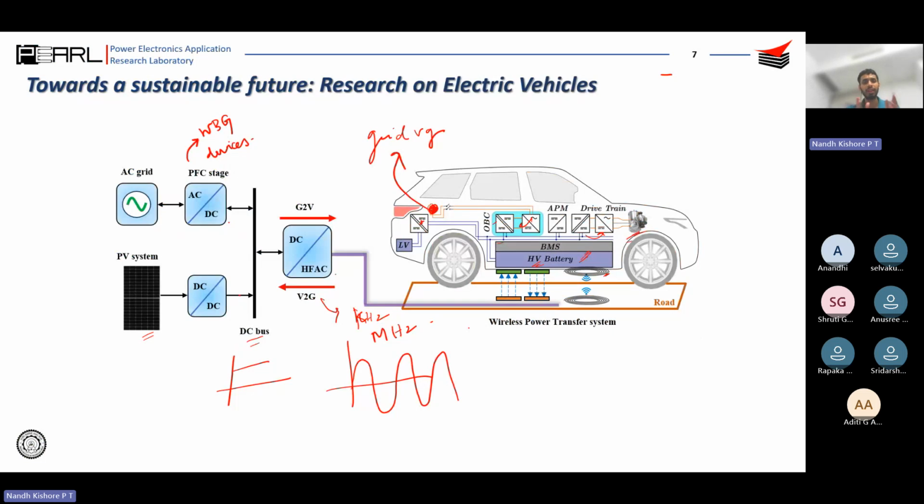You understand, right? So there is a lot of power conversion involved over here. First, there is an onboard charger to convert whatever you supply from the outside. You just plug in some voltage, so there is an onboard charger to charge up the car battery. From the car battery, there is a power electronic converter to convert the DC into an AC voltage and run the car motor. Lot of power conversion involved.